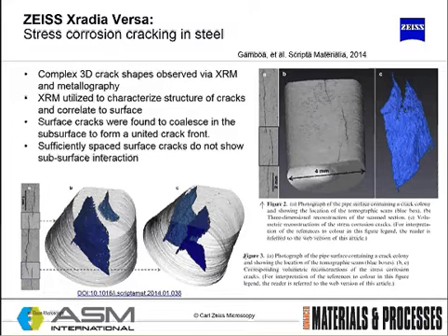And if you do want to verify that information in 3D, you'd require cutting open the sample, but that's dangerous because you can possibly create new cracks or change the geometry of the existing crack in the process. XRM presents a nice solution because we can look at the interior crack geometries without cutting the sample open. And then the software is able to isolate in 3D, produce a model of that specific crack.